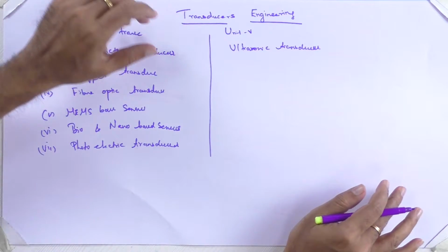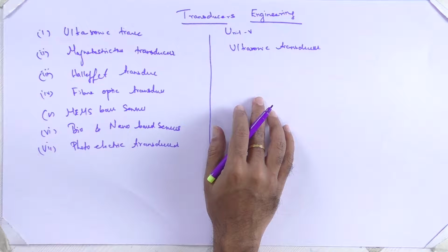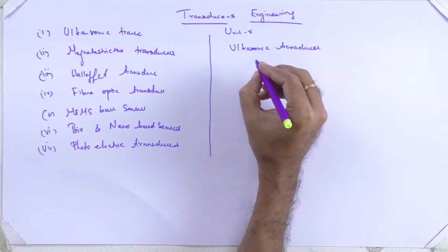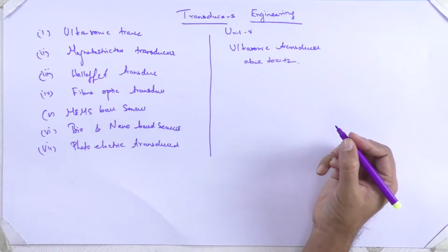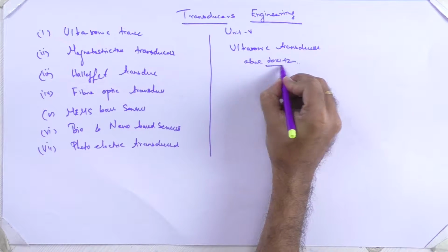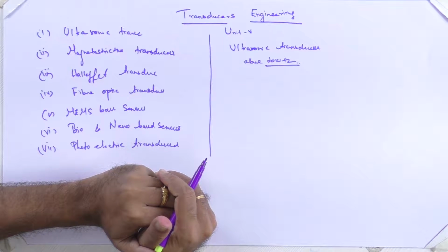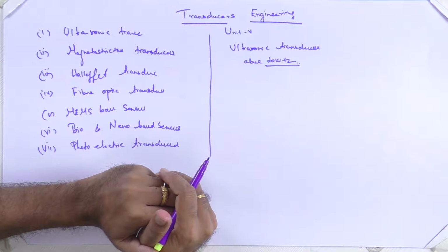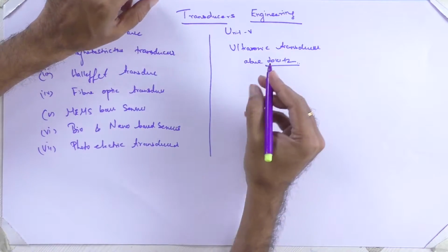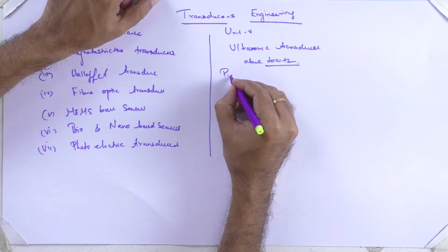As I have already given in the previous note, ultrasonic transducers work in the acoustic frequency range of above 20 kilohertz. They are mostly used in proximity or obstacle detection and in level measurement, and all other kinds of applications where there is going to be an obstacle present in the area. The ultrasonic transducer always has a piezoelectric crystal